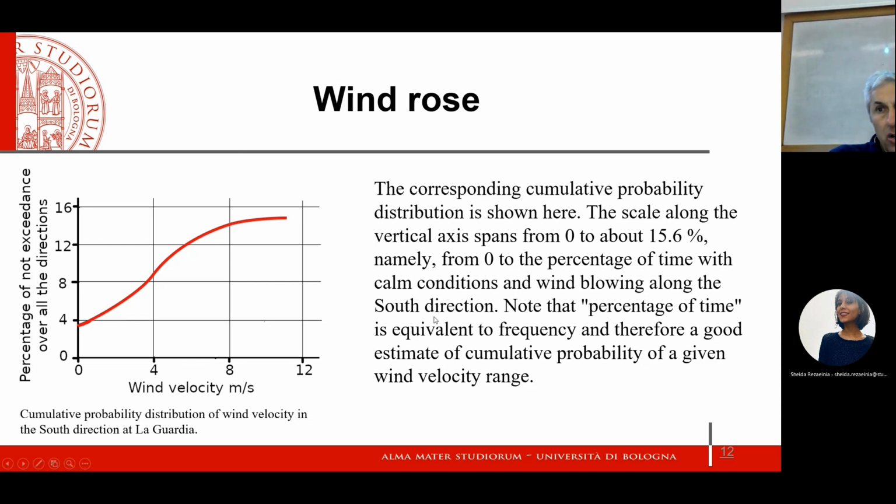So be careful of the quality of the data that you have, quality in terms of both uncertainty and length of the observation period. Whenever you use data, you have to be very mindful of the so-called metadata: the additional, associated information, how it was measured, the height of the anemometer. If it's 10 meters, it is a different story with respect to 2 meters, etc.